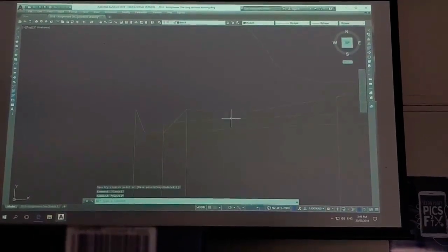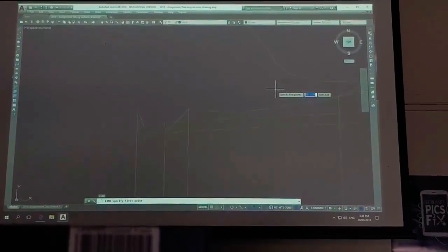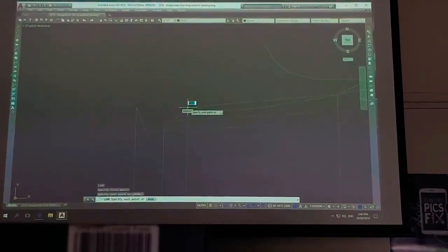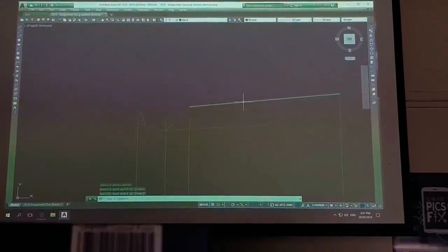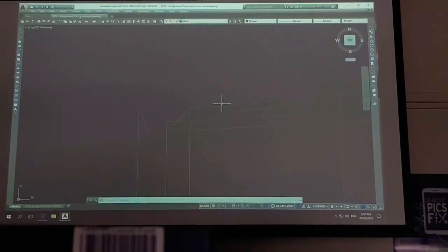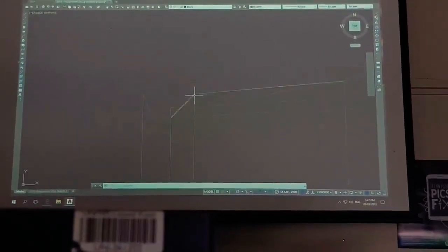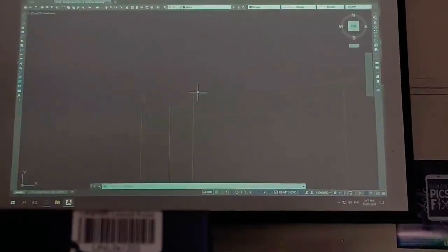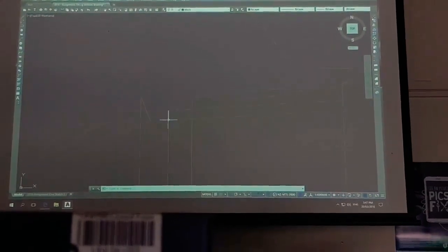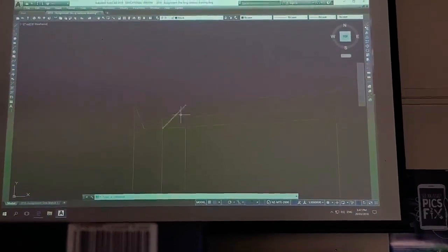So here's a very low point, and I would suggest, now listen, you're not qualified engineers, but I would suggest a note from there to there saying that an engineer needs to investigate whether we need some more fill there. Okay? And I would also suggest that if that's where the creek starts, that's where your outlet structure should start. So it will poke through quite a bit. Alternatively, you take the outlet structure into the creek further down, which I don't think you would do. I think you would take it right back to the beginning of the creek.